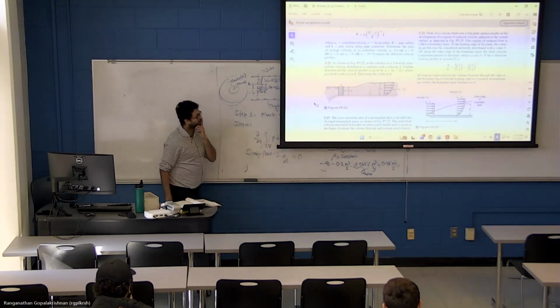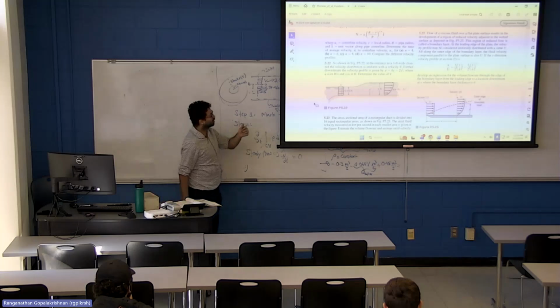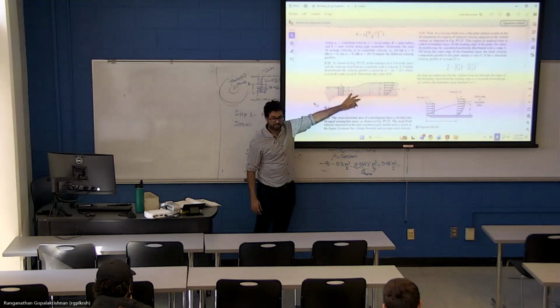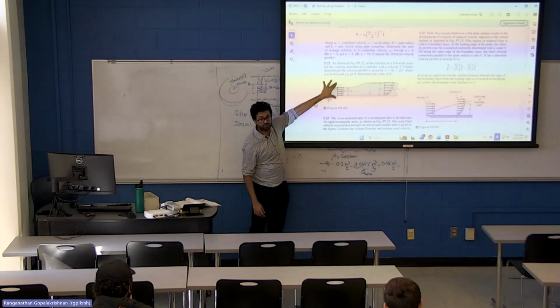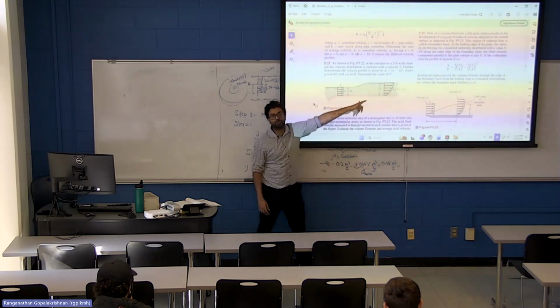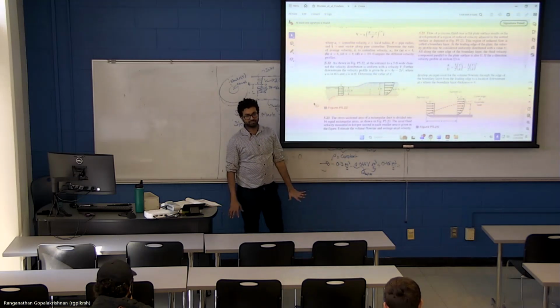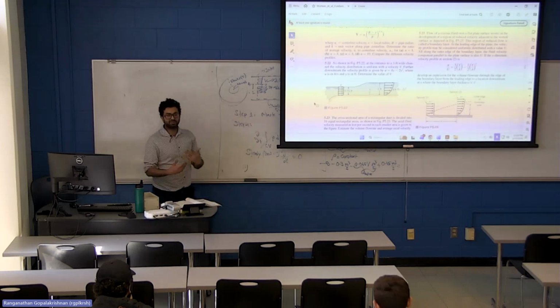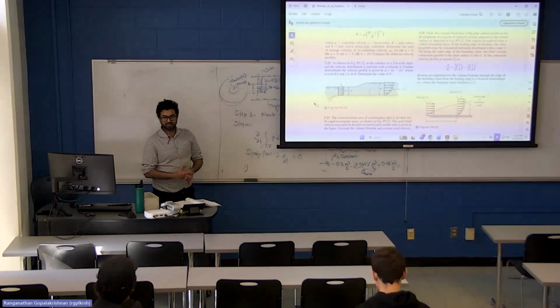That's intuitively the steps. Okay, and now we'll put it in math. Steady flow, so there is no change in mass. Inlet velocity is uniform, that's easy. Outlet velocity is non-uniform, so you do integration. That's all. Why don't you try this and then we'll converge and check our answers.